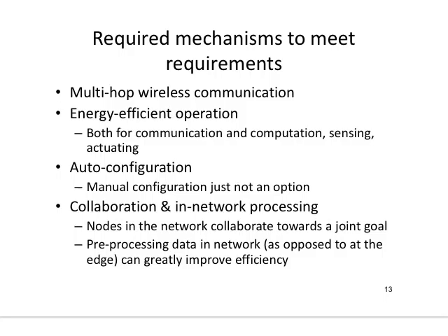Even sensing and actuating is another aspect that I need to optimize, because if I'm sensing more frequently, I'm again utilizing more energy. So I need to sense whenever I have to, or whenever I need actual information to be sent. If I don't need to sense the information now, then I'd rather be in a sleep mode or not doing any type of sensing. So the three major components that consume energy are sensing, processing, and communication, right?